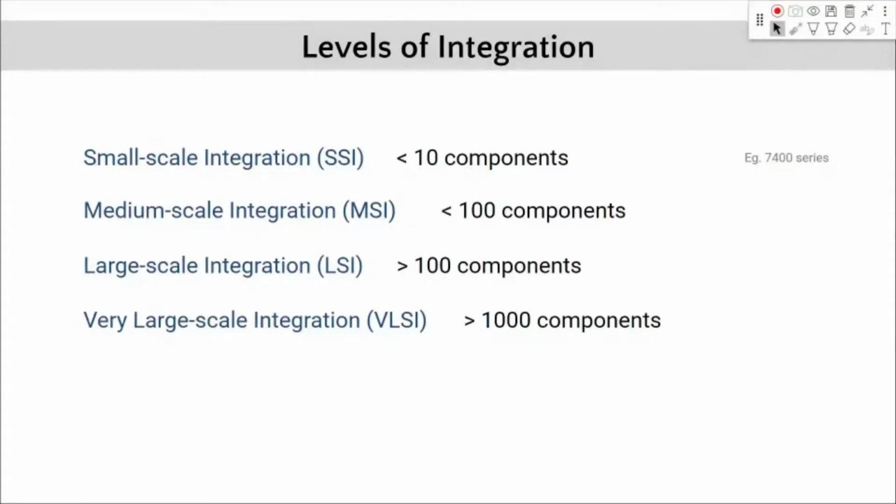When we talk about medium scale integration, here you will have ICs that contain decoders, adders, multiplexers, like single ICs which contain this entire circuit. So you know that they will need more than 10 gates, of course. Then LSI has processor chips or memory chips, RAM, etc. Then in very large scale integration, VLSI, you will find an entire microcomputer built into a chip, which will come under VLSI integration.